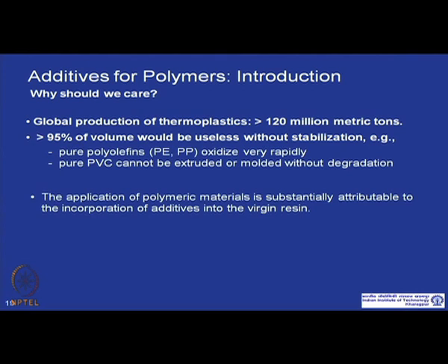The successful application of polymeric materials is substantially attributable to the incorporation of additives into the virgin resin we just produce from the reactor. If we do not use additives in the resins coming out of the reactor, their applicability will come down drastically.